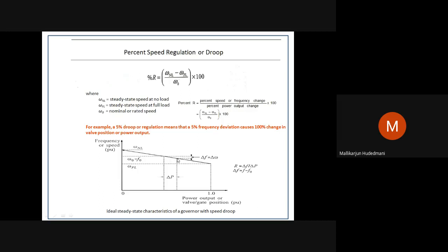It may happen that there is a further load increase. It may repeat, and again it will fall down. Again, the governor will adjust it. Likewise, you can go without the governor or with the governor. Without the governor, when I operate this machine, naturally the frequency keeps falling down and down. It may go to a non-acceptable state even though the machine is delivering full load.